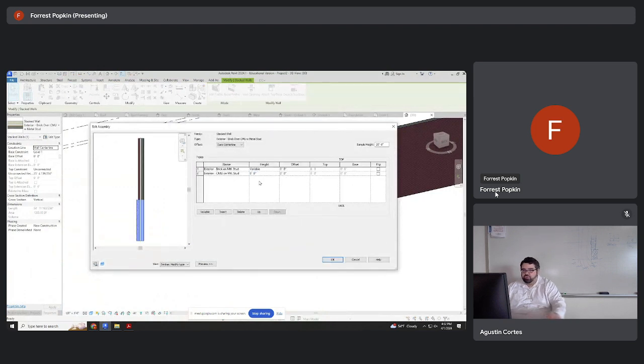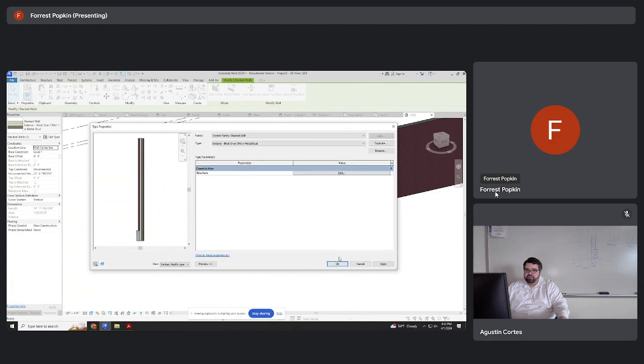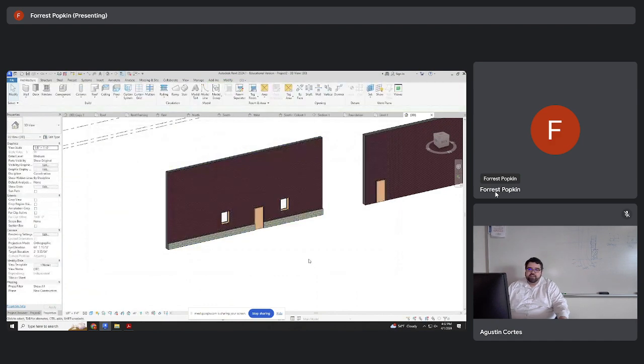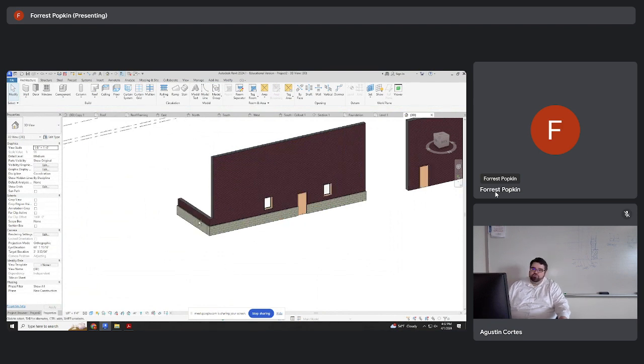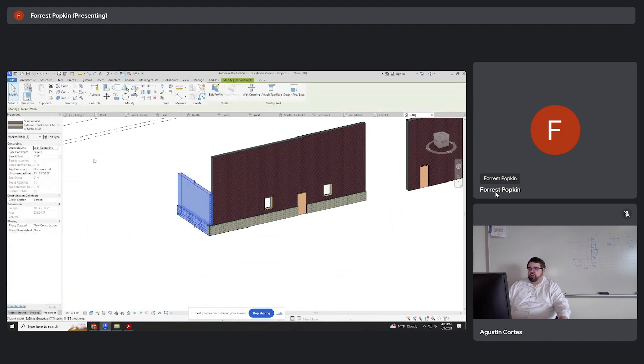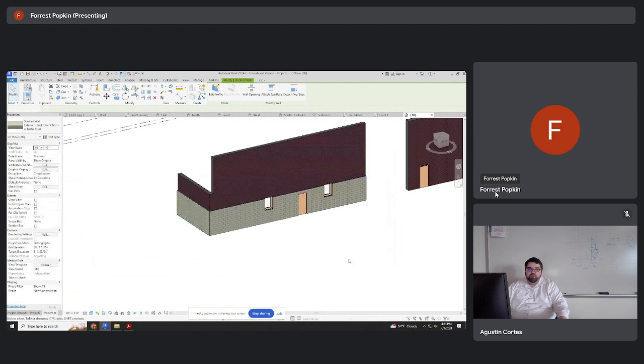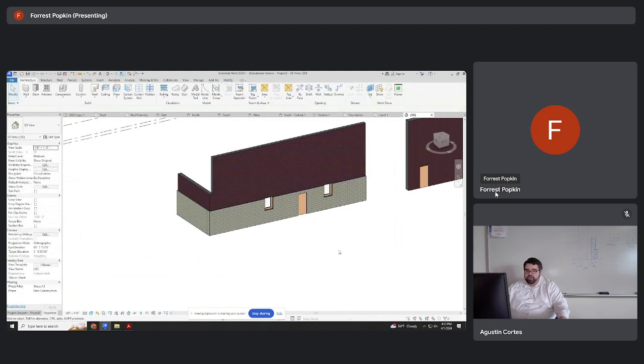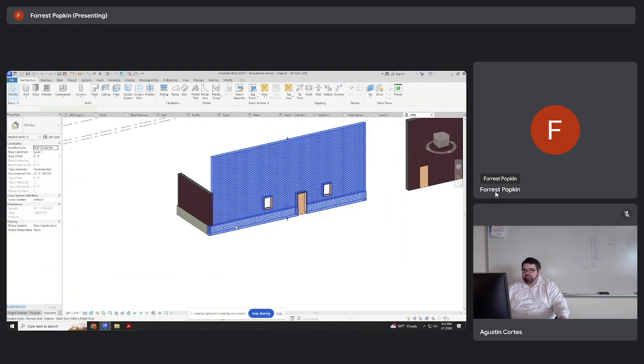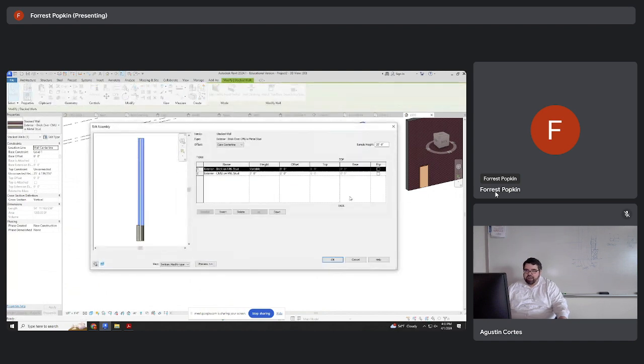So again, if I go back to something that's going to be a little bit different, I could also make this very short, and I could say I want this to be 2 feet. Okay. Now you'll see it deleted the wall that used to be here. That's because my wainscot was so tall. They said, well, I have to delete this, otherwise it doesn't make sense, right? So you gotta be careful. If I'm gonna make it 8 feet, you gotta make sure my wall is actually tall enough to receive that. Now that I modified that, the whole thing can go up again.